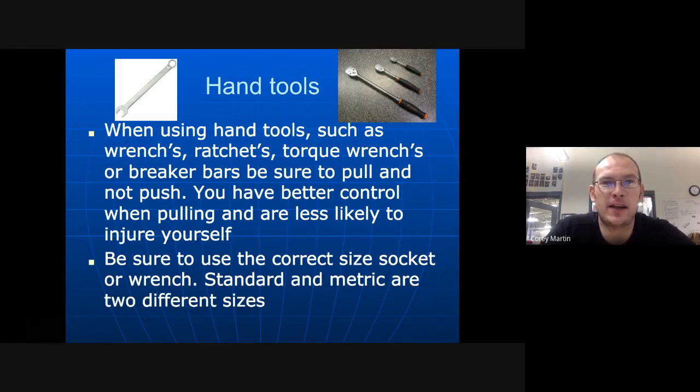Okay, a couple of examples of hand tools here. We've got a picture of a wrench and then three different size ratchets. When using hand tools such as wrenches, ratchets, torque wrenches, or breaker bars, be sure to pull and not push.